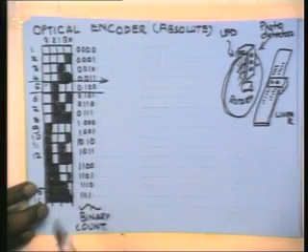And if I just happen to read it at this transition, then I will not be sure what value I will get. I may get 0, I may get 1, I may get 2, I may get 4, any of these, depending on exactly how the timing, the precision of this particular edge is, which cannot be predicted. So this is a flaw in this type of binary pattern, which can be overcome.